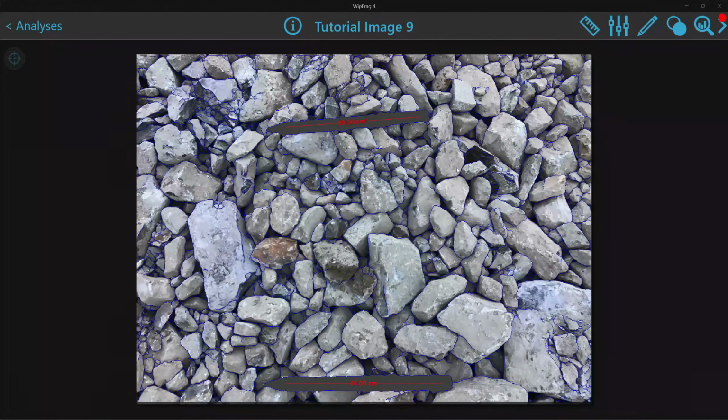There are a variety of editing tools available to edit the net. First, we will go over what each editing tool does. Tap the Edit Tools icon in the toolbar to open the Tools menu. The first tool is Free Draw. Click and drag to draw net anywhere. Undo. At any point you can undo previous edits by using this button.